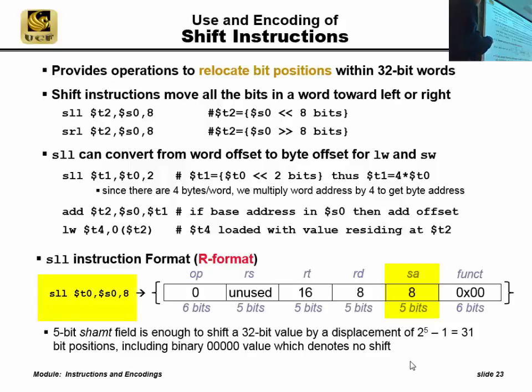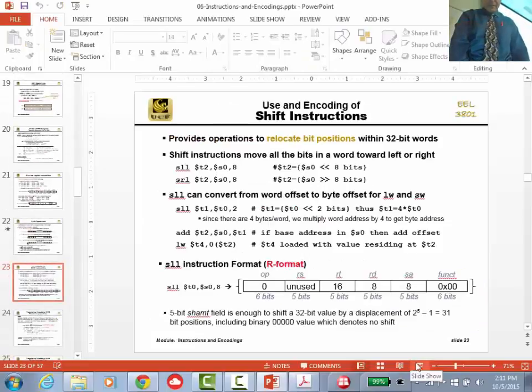Because this instruction had 8. Here the shift amount would be 2 if I wrote the bit sequence for that, but this is the bit sequence for this instruction. The shift amount is 8. What about the rest of the instruction? Well, the opcode, SLL, is actually 0 for the op and 0 for the func. Let's take a look. That came from the data sheet.